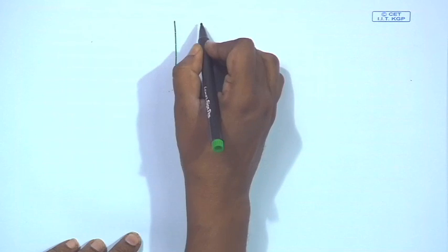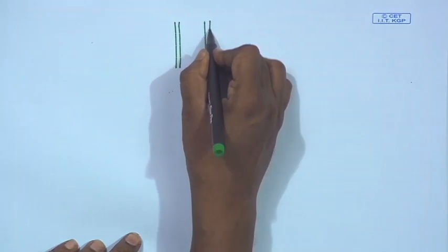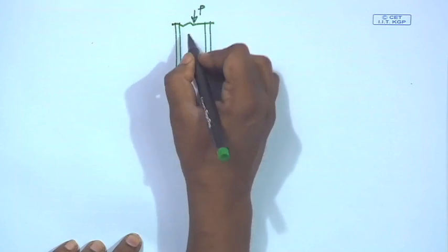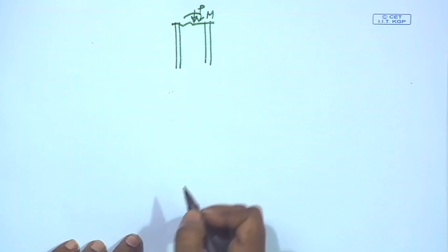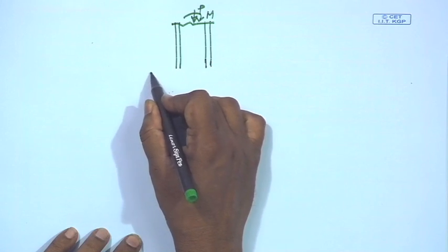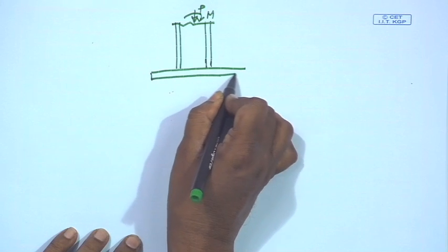Now, let us see the general assembly of the column base, means the slab base. Say for example, in this case an I section is transferring load from the superstructure. It may transfer concentric load, and also it may transfer some moment as well, and then we provide a base plate of steel material.